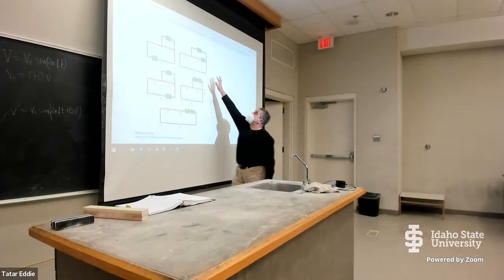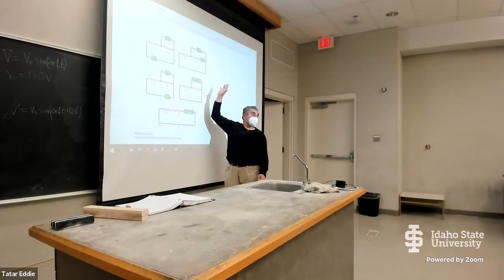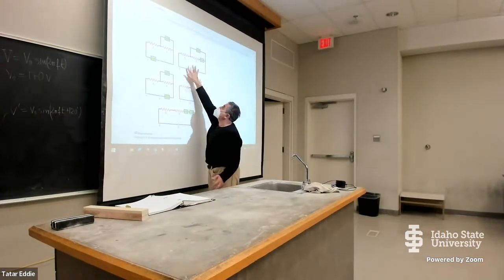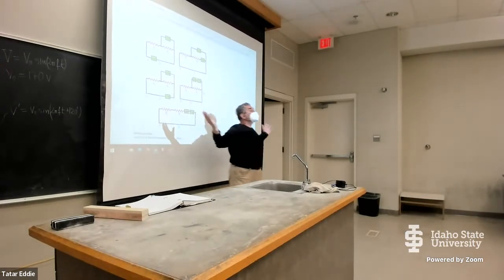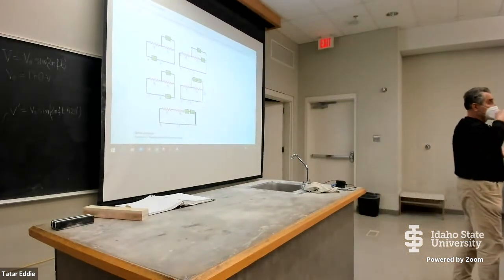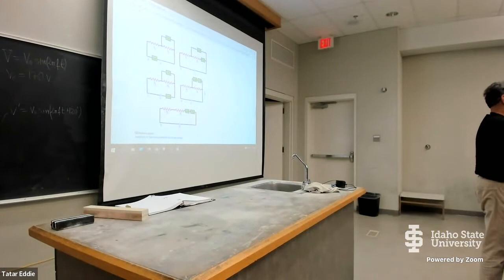If VM and AM were switched in the second circuit, it would be perfectly fine. So you can put the ammeter here or here or here or here. Everywhere the current is the same, it is going to measure exactly the same current. But those are good questions. Keep asking questions like this. This is the only way to make sense of those circuits.